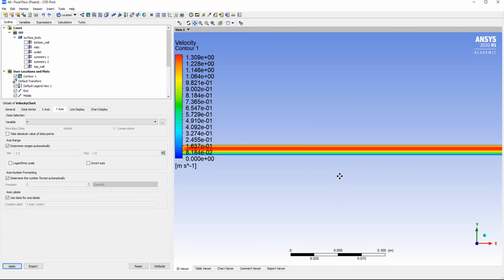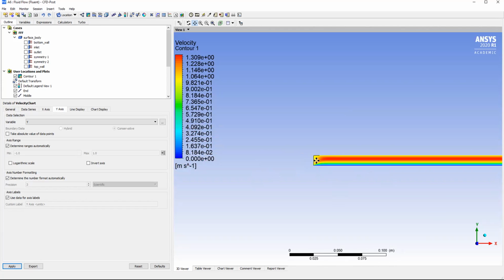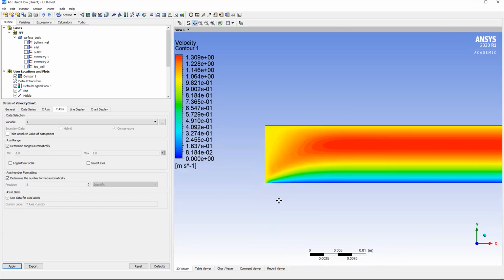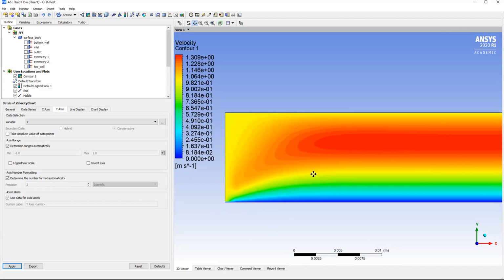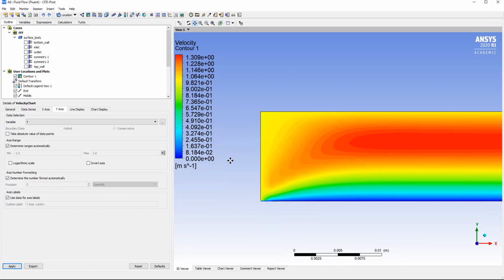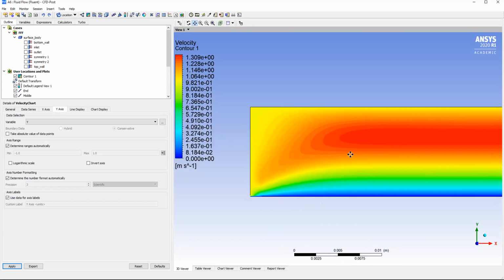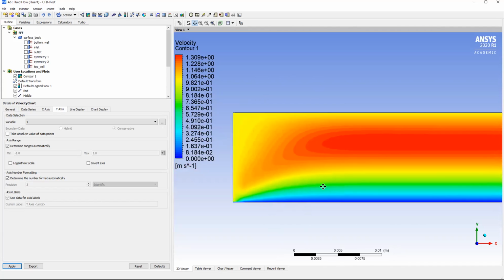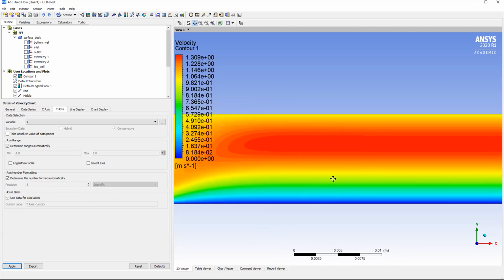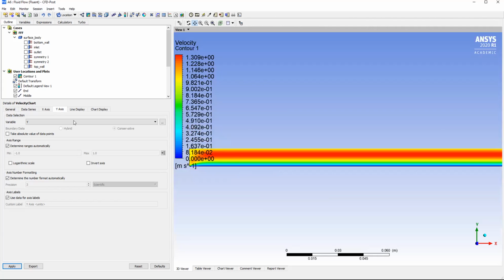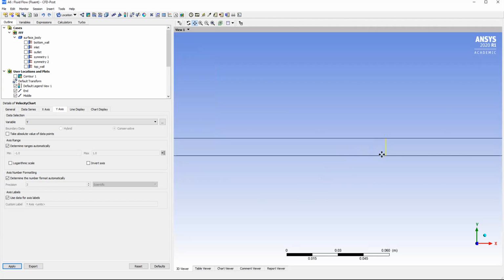So that is actually all that I wanted to show you for today. Oh, don't concern yourself with the very beginning. Like before with the Couette flow, it's just small development of the boundary layer happening here. So I suppose it does need some time for this bottom boundary layer to develop before it fully develops into this part. But you can see that there is very little distance necessary to actually fully develop the flow into the combined flow. And we didn't see this region here because we never even put lines there. Our lines are starting here.